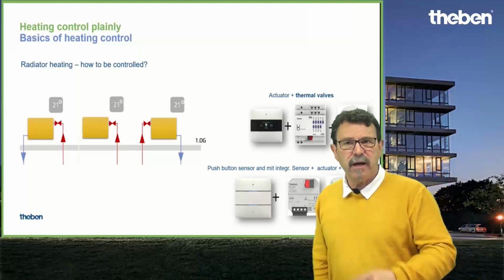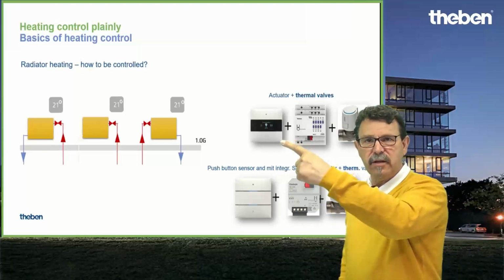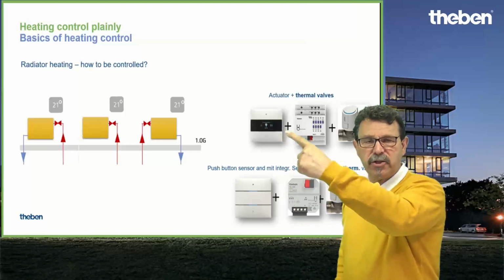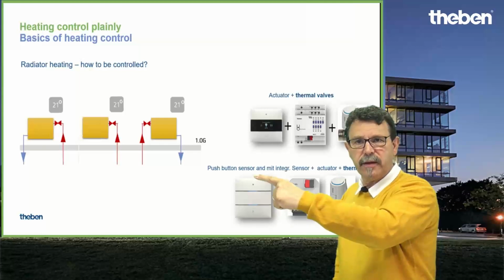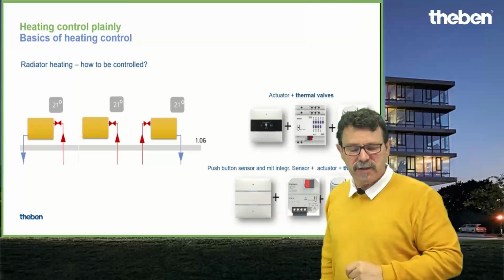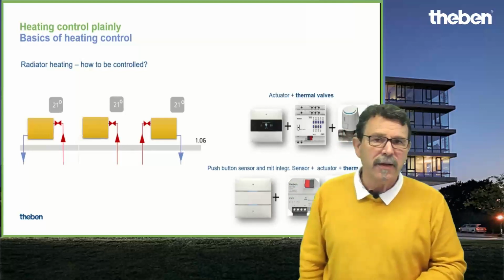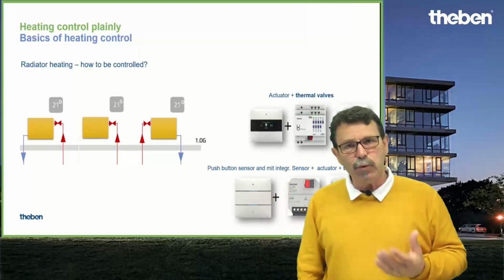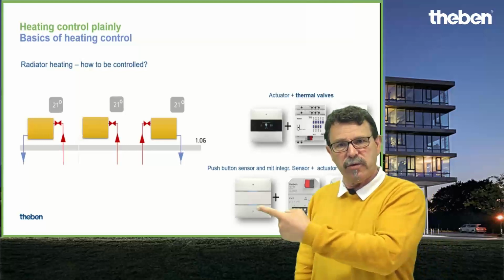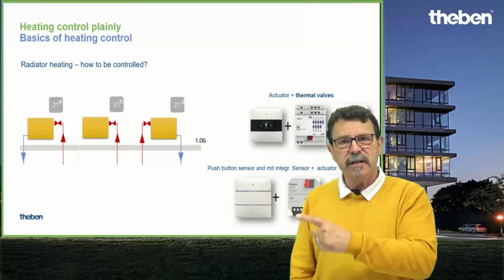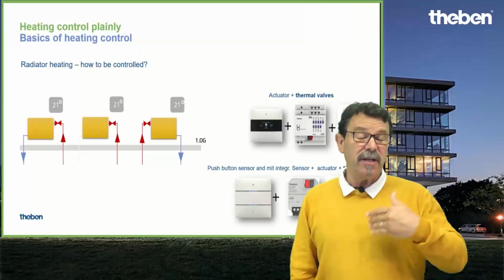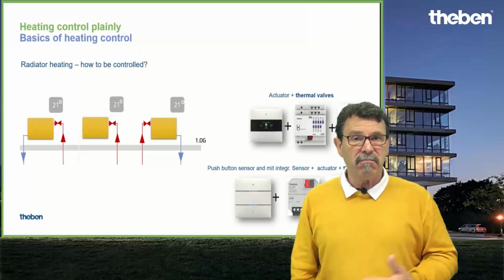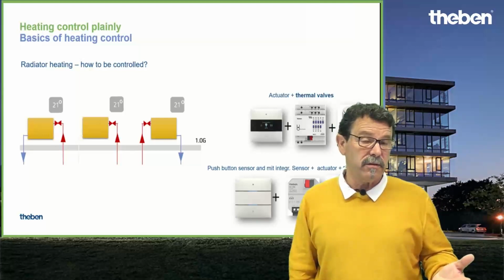And the room temperature controller, for instance, either with the external remote, so you can adjust your set point, or here you have the temperature probe, which is inside this push button. And with this room temperature, which is measured here with the Eon 102 in this case, you address it to the heating actuator, which is to be set as a controller, and then the heating system is running on its own.